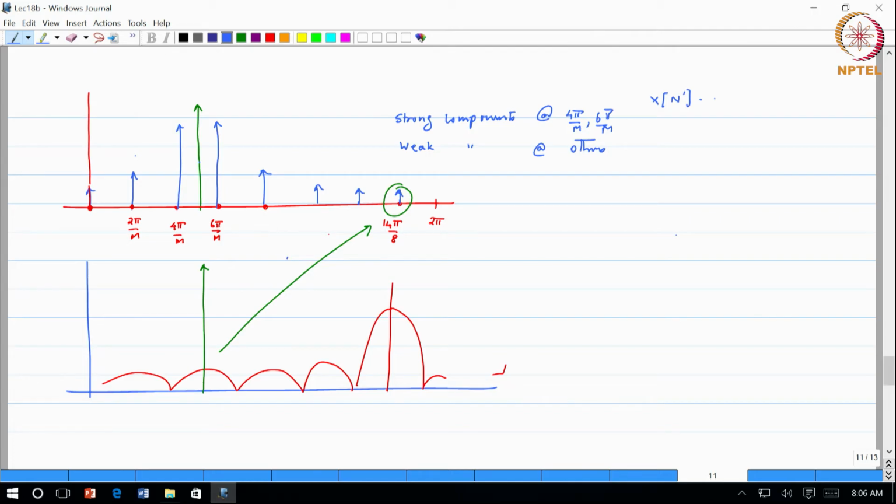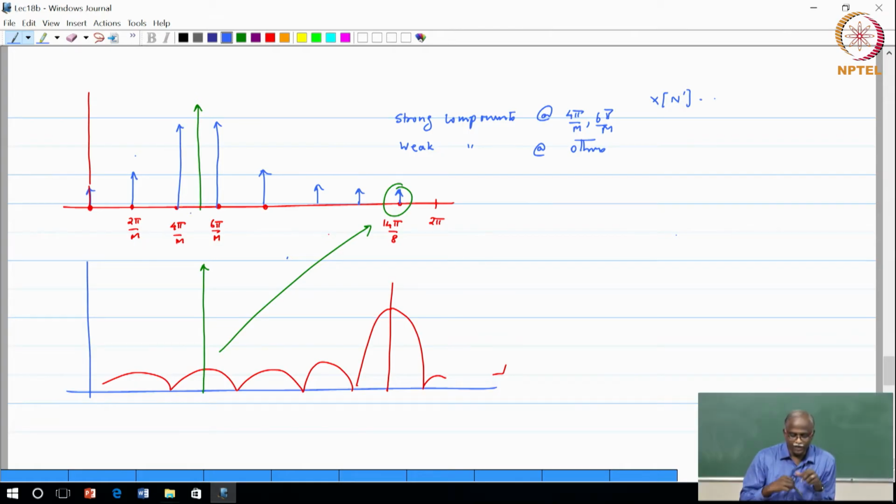If my input signal has a single tone which lies in between two DFT frequencies, you will find that all of them have non-zero values. What is puzzling is why a frequency component far away from my tone would still show something non-zero. The reason is that it is not a delta function; it is actually a filter that is looking at the input spectrum. So some component comes out of it, and that is what shows up as the DFT coefficient.